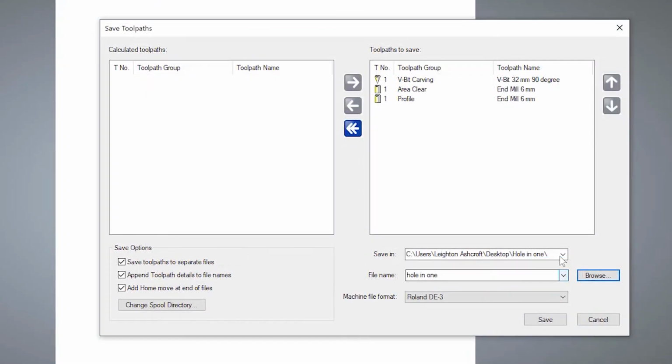Select Open, and then that becomes the active folder that it's going to save in, and that's the file name. Now, I have seen people do this where it just goes directly to the CNC machine over a network. So you just need to browse to the CNC on the network, and it would automatically place it on the CNC's memory. Now, it doesn't do that for every machine. I've just seen it on certain machines.